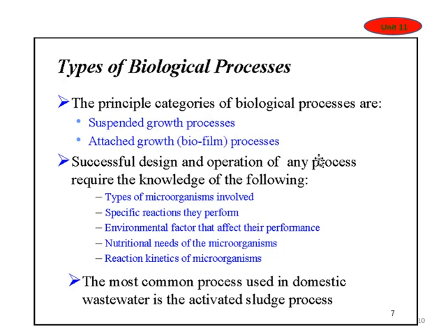In the suspended growth process, everything is in suspension in a big tank in the water. In the attached growth process, we grow the bacteria on some solid material like the stone and other things, and then we pass the wastewater through that to treat it.